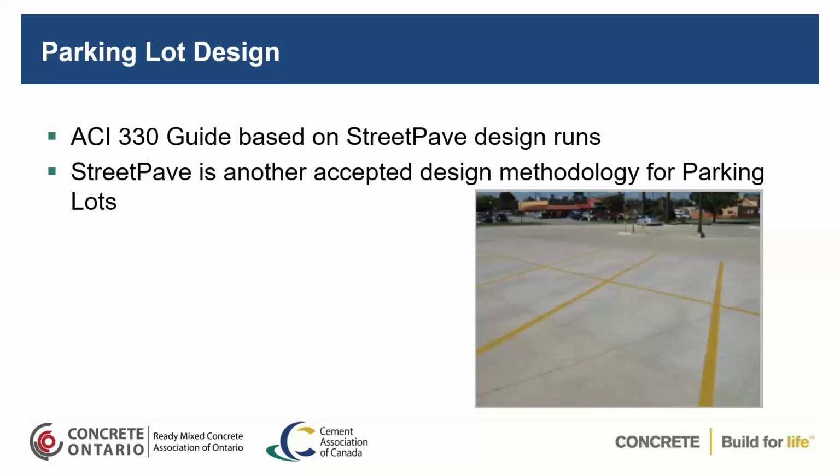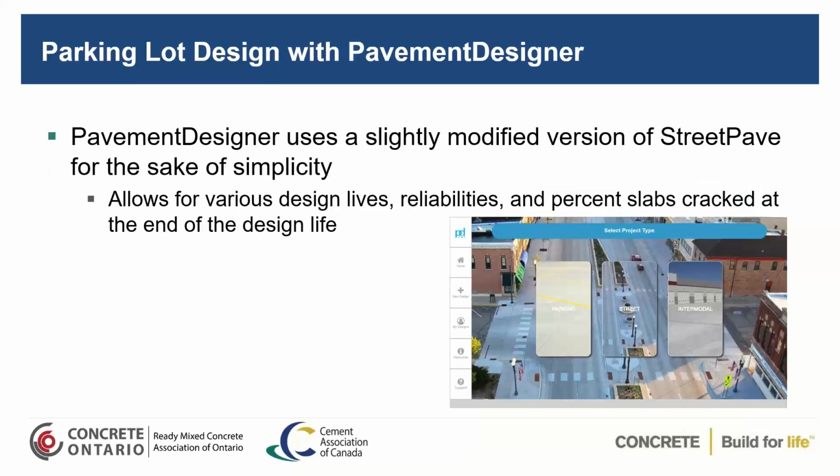Now, the key thing about parking lots is that you don't have the same channelized traffic that you would on a conventional roadway, so you can actually have a much different footprint of your analysis. You can go with a thinner pavement structure in your parking areas because you don't have that channelized traffic.